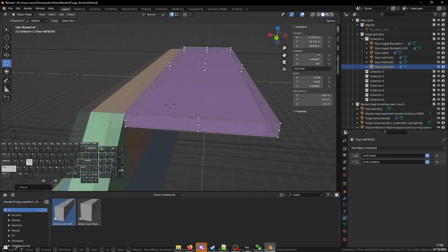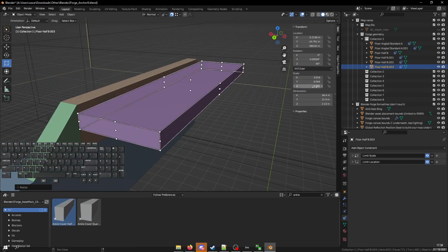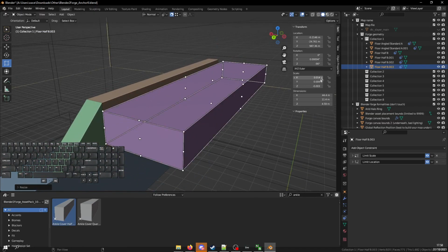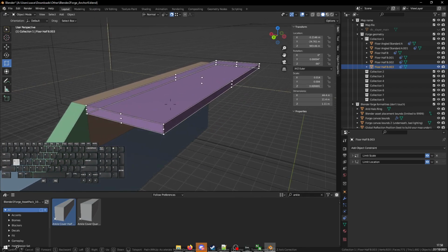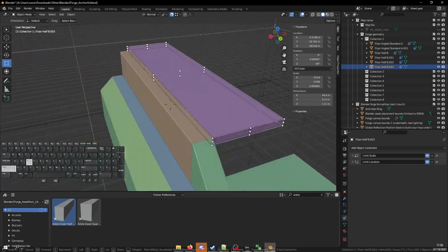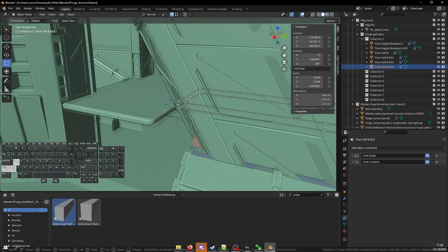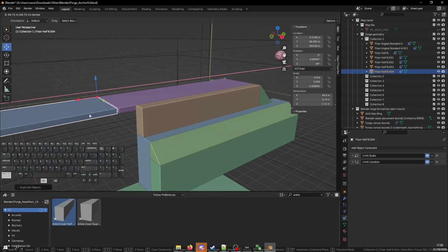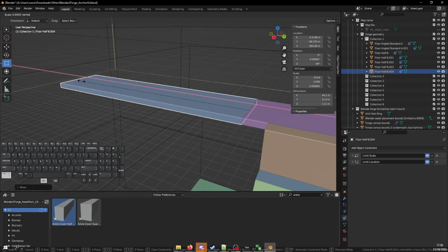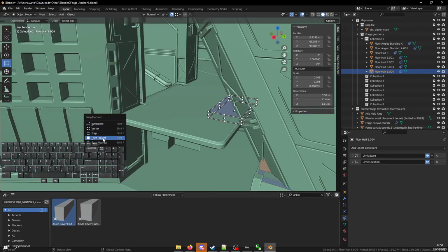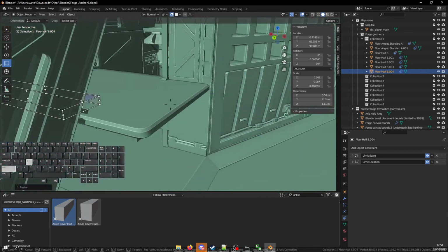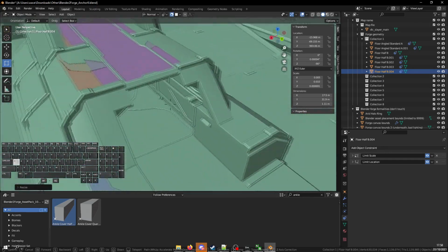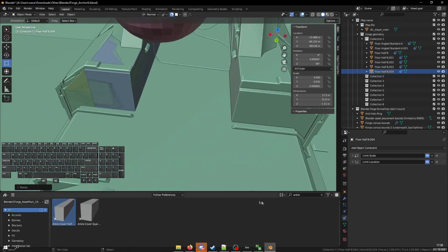If your object goes to negative scale like this, so you'll see here we're getting negative values, you need to try to see that as early as possible, because if you're trying to print an object with negative scale, it won't print correctly. Just keep an eye on that. You don't want that to happen. Let's place a floor here.